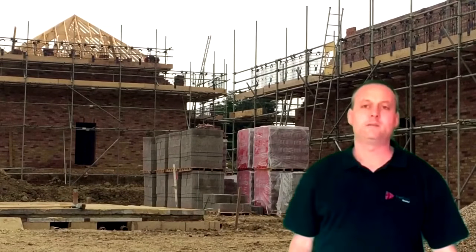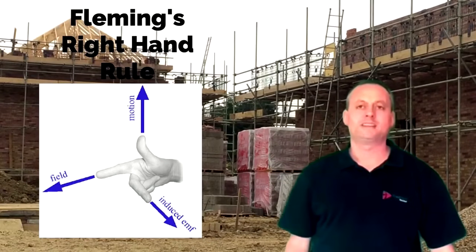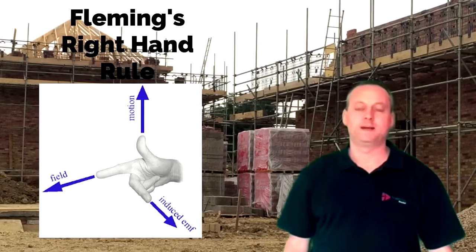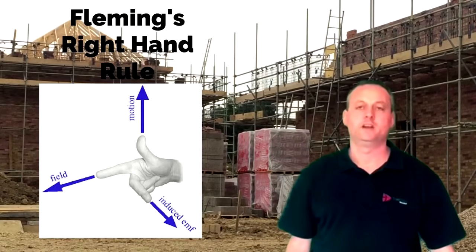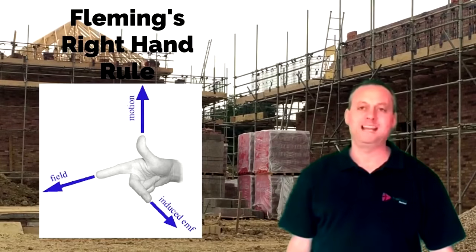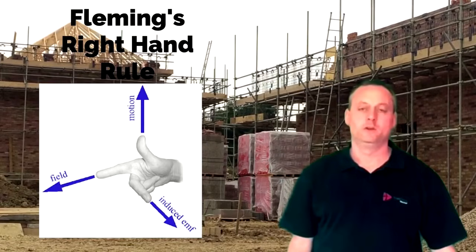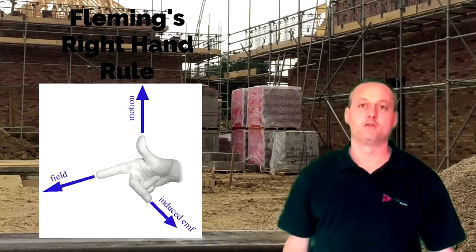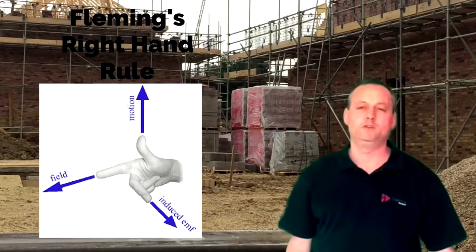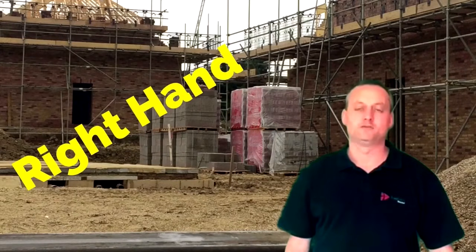On the back of Fleming's left-hand rule, we went on to look at Fleming's right-hand rule. This time, we've got a conductor being placed in a magnetic field, not a current carrying conductor, a conductor. And we're going to induce an EMF into that conductor. So in other words, the basic principles of generation. And sometimes they call Fleming's right-hand rule, not necessarily just the right-hand rule, but the generator, as in the right-hand rule. So when you're reading a question in the exam that says a conductor is being placed in a magnetic field in order to generate an EMF, which hand will be used? It will be Fleming's right-hand rule.